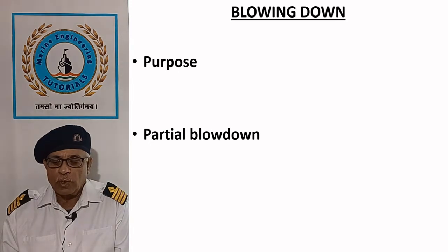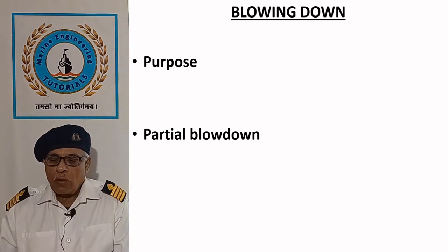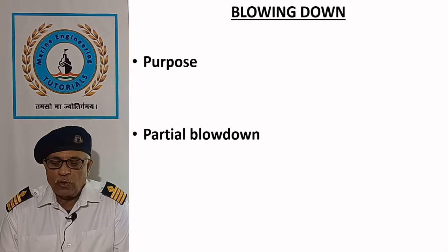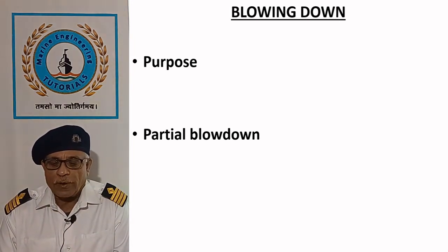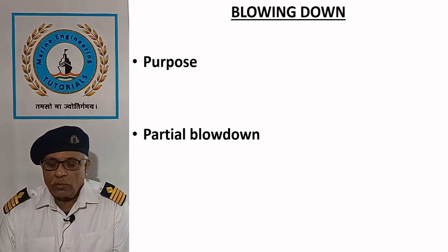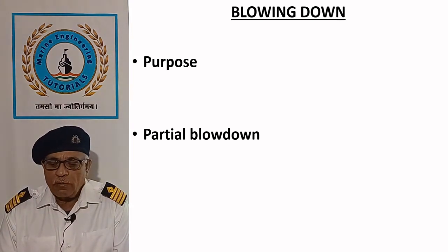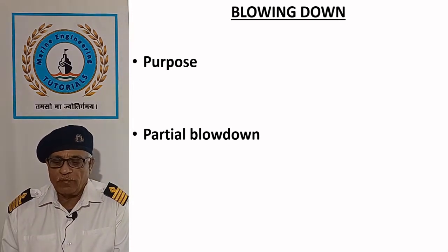Partial blowdown. Partial blowdown is carried out when the boiler is in operation and under steam pressure. Blowing down can be monitored by the noise caused by the condensation of steam.